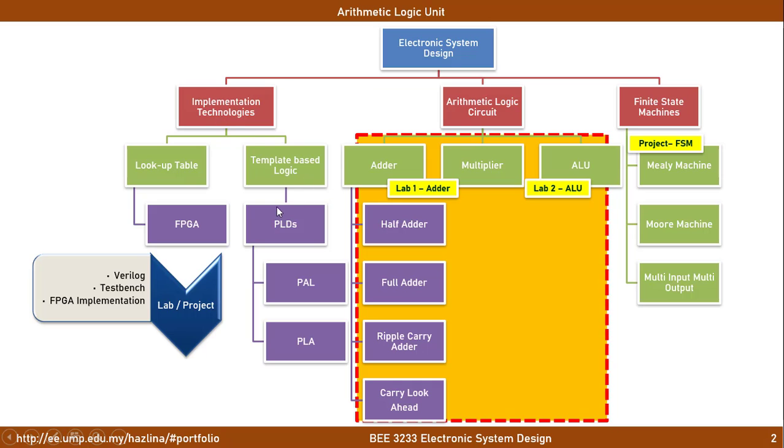We had started off with PLD, Programmable Logic Devices, in which we had looked into two methods. The first one is Programmable Array Logic, and the other one is Programmable Logic Array. Secondly, we move into FPGA, in which the concept that is being utilized by FPGA is by using lookup table.